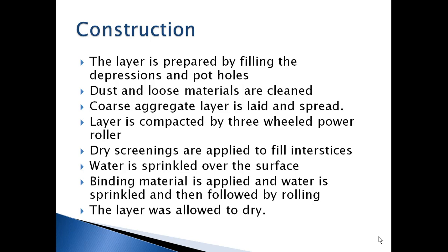The construction procedure is: on the base layer, if there are any depressions or potholes, they are filled. Then if any dust or loose materials are there, they're cleaned up. The coarse aggregate layer is laid and then spread. The layer is compacted by a 3-wheeled power roller.